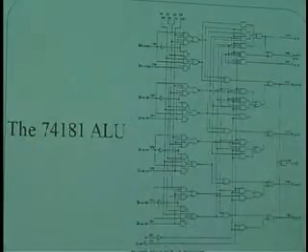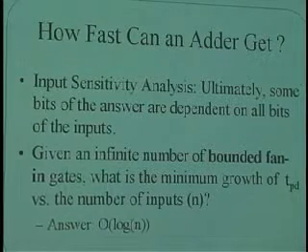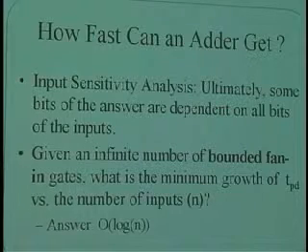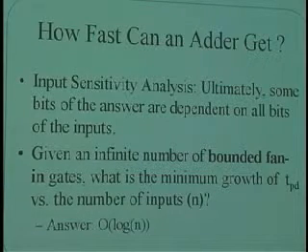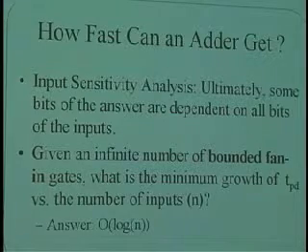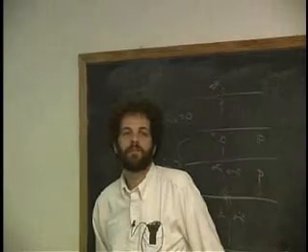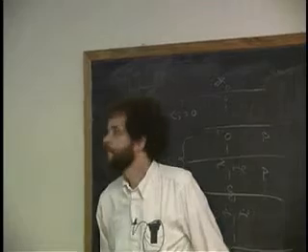Let me talk a little bit about how fast things can get. How fast can an adder get? Well, ultimately, if you're adding two numbers, A and B, the answer in any given bit may depend on all the bits of the inputs, somehow, right?